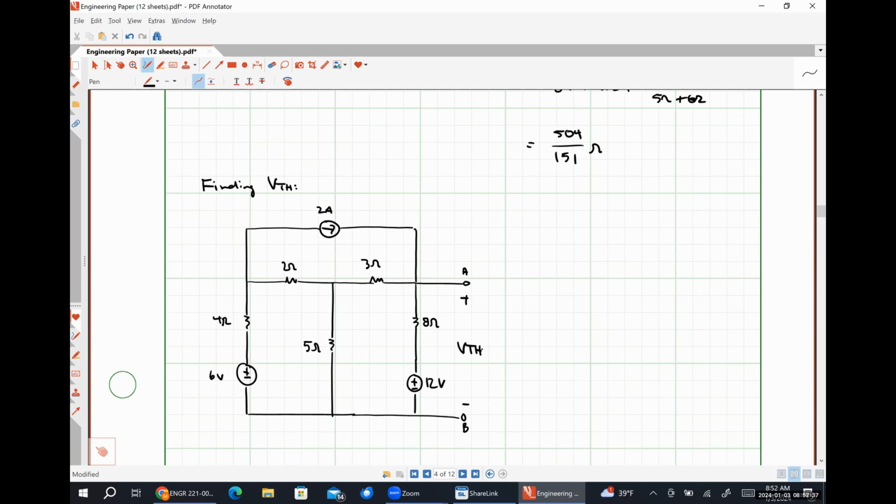All right, so let's run through some things. This circuit is fairly complicated, so there's not anything obvious that's screaming KCL, KVL, Ohm's law, voltage division, or current division. All those are kind of out the window for a circuit this complicated, which means we really have to choose between nodal and mesh. So let's talk through that.